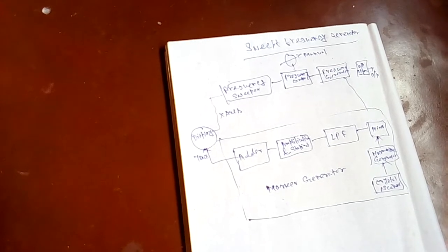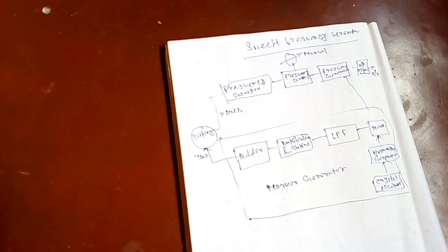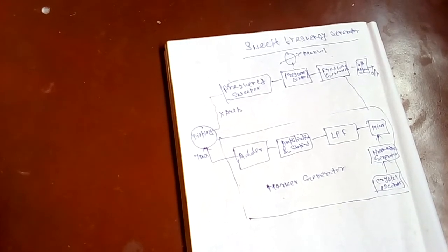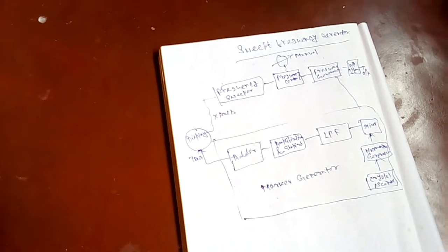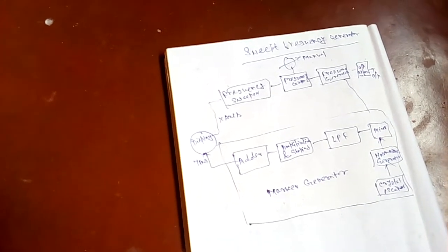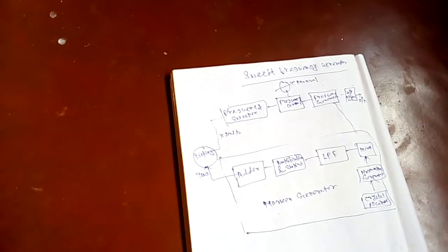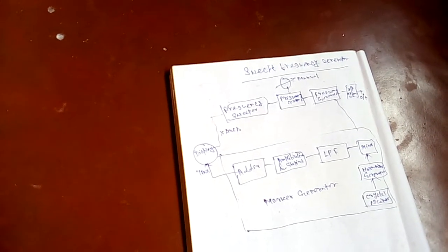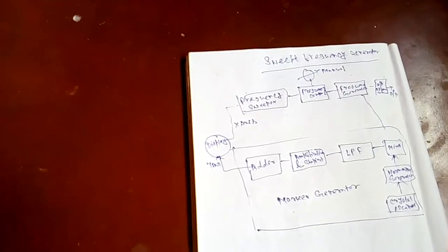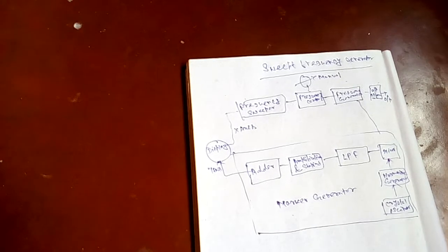This mode is used for wide sweep width, when we need a wide frequency range. Another mode is the delta frequency mode. In the delta frequency mode, there is some maximum deviation of the frequency, set from the panel, and it is used for narrow band frequency width.